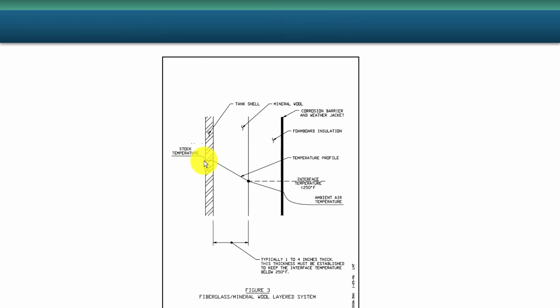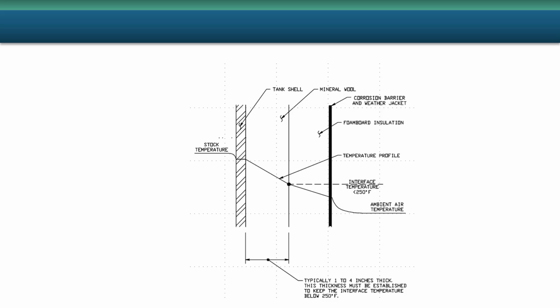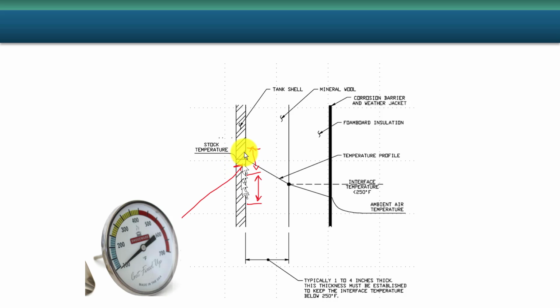In insulated systems where it's careful to maintain the temperature here, if this gets wet, this heat transfer line will, at this point here, even though the outside and the inside temperatures are the same, the slope of this line can go up and down, and the surface temperature will change. So for example, in a cold tank, the line would be going up instead of down. But in a cold tank, if this starts sweating because you can't maintain the temperature properly above the sweating or condensation point, you'll get aggressive corrosion. And that will happen if your insulation gets wet and is no longer maintaining the proper temperature. What I was talking about, this temperature of the steel will move up and down to the wrong regions, and you'll get accelerated corrosion.